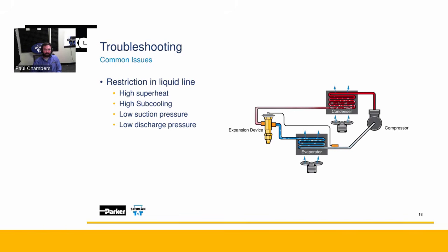When we initiate a system, we start it up for the first time, we've brazed, we've soldered, you might have oxides on the inside of the pipe from not proper purging or something like that. Really easy to clog those.